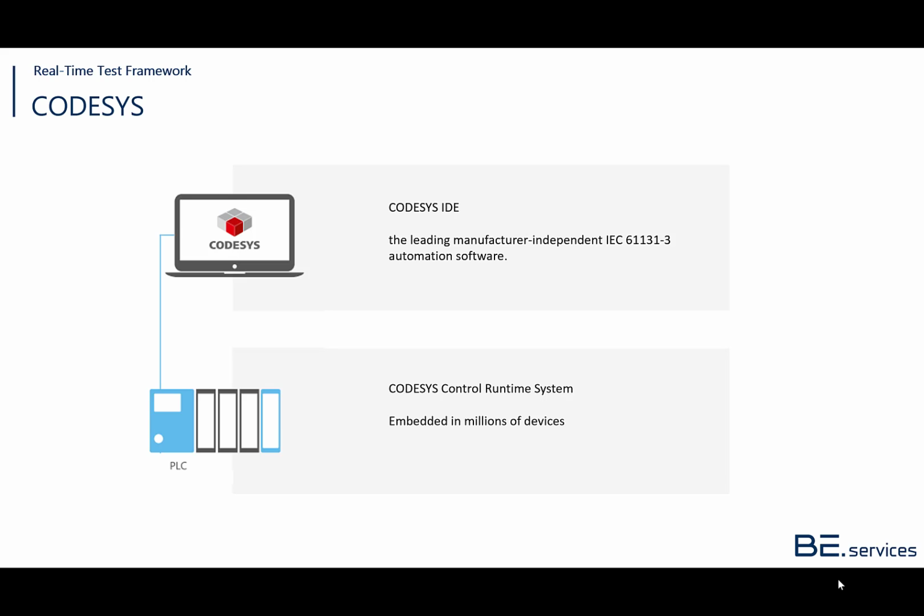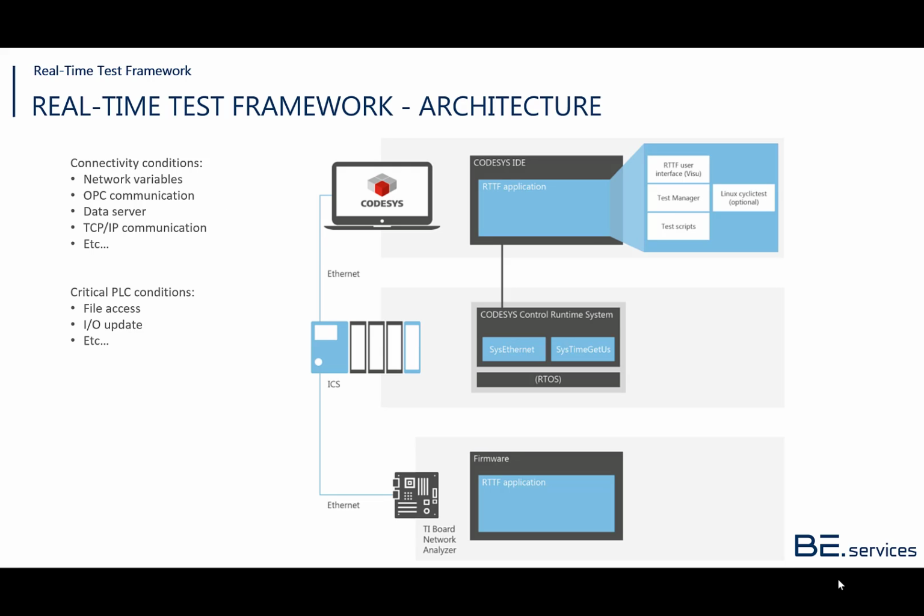Applications developed with the IDE are then executed by the CODESYS control runtime system. It needs to be pre-installed on the controller. The RTTF is fully integrated in the CODESYS environment and allows testing any ICS that embeds the control runtime system and implements two key components, SysEthernet and SysTimeGetMicrosecond. The operating system used on the device has no importance as long as these two components are implemented.